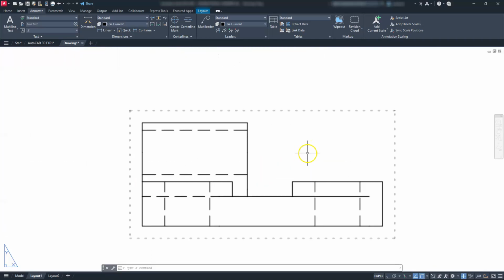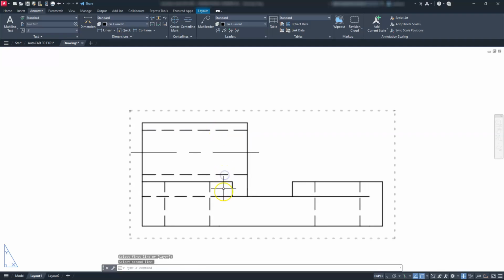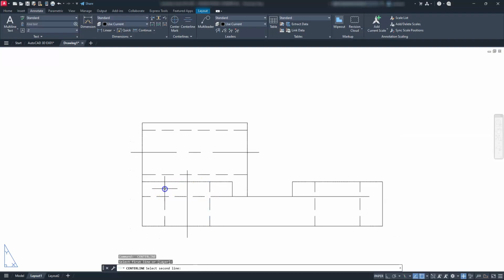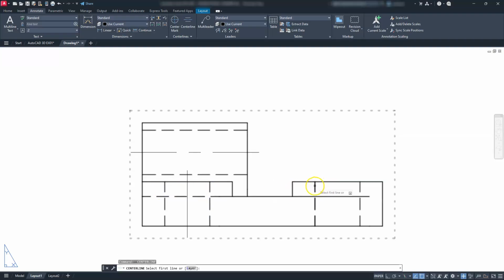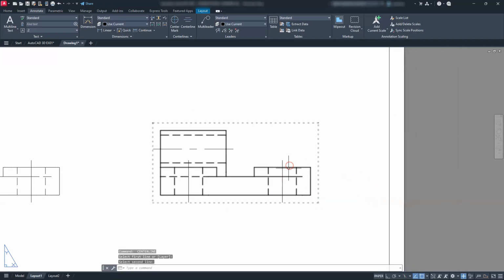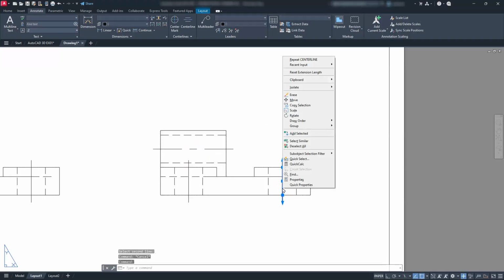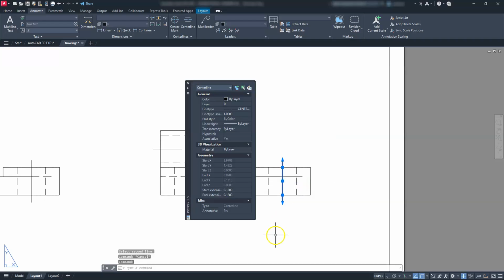Okay, let's go ahead and take a look at here, and then we're going to put these center lines that are located along here as well. And we got one more to do. Okay, so with the ones that are not showing that extra line in the middle there, what I usually like to do is I'll select one of them, do a right click on them, go to the properties, and what I usually play with is the line type scale here, right?